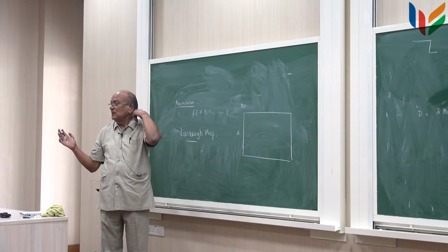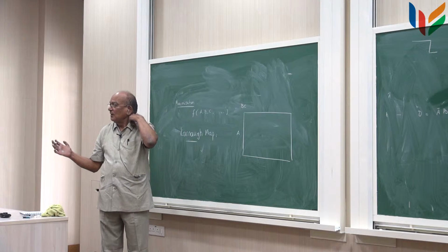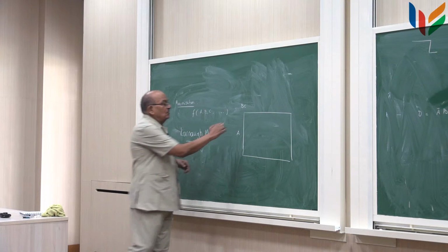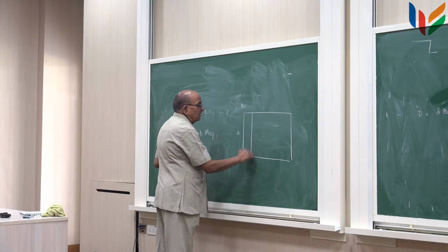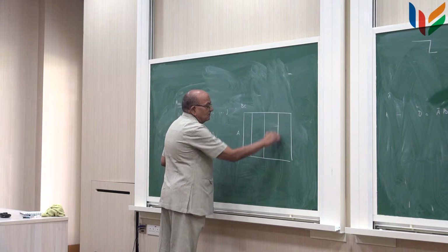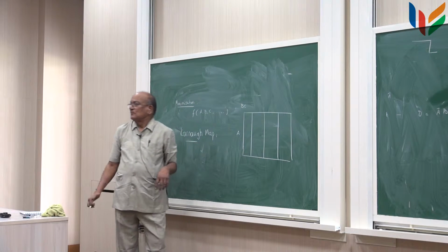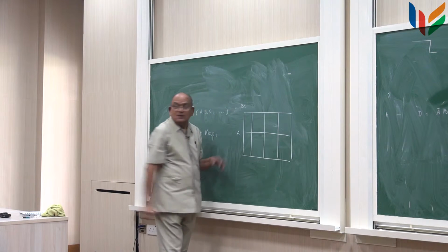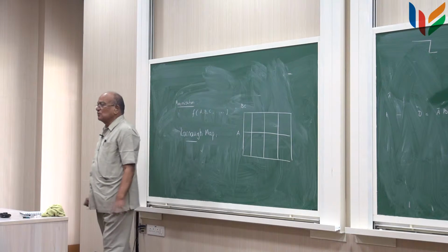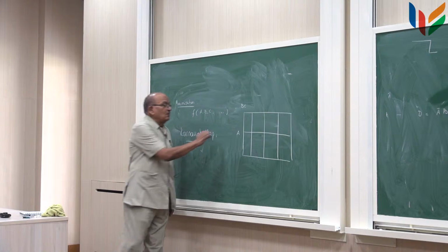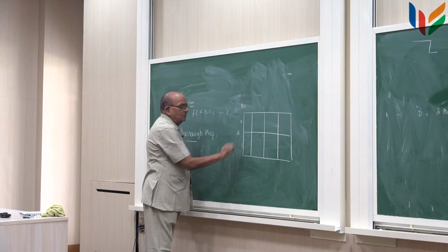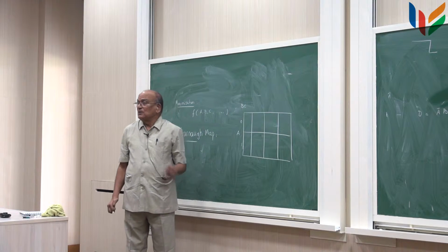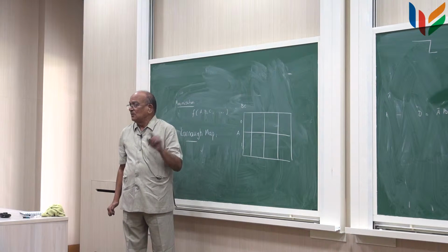How many combinations can it take? 4 combinations: 0 0, 0 1, 1 0, 1 1. So because of the 2 variables here, let us make it 4 columns. And this one is only 2 possibilities, A, so either 0 or 1. This BC will be 0 0, 0 1, 1 1, 1 0.